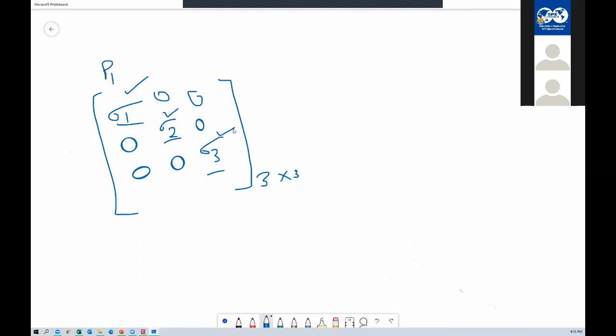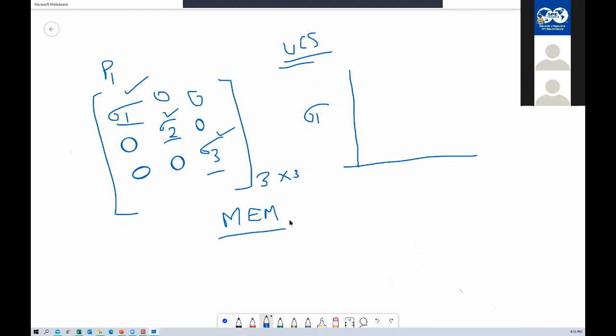Why do we want to do that? Because only then will we be able to understand, with the given values of sigma 1, sigma 2 and sigma 3 and rock strength, whether our rock is going to fail or not, whether this rock is going to deform or not. You understand the logic, guys? So in the mechanical earth model, we will estimate stresses as well as elastic and strength properties of the rock. That's all the mechanical earth model is about.